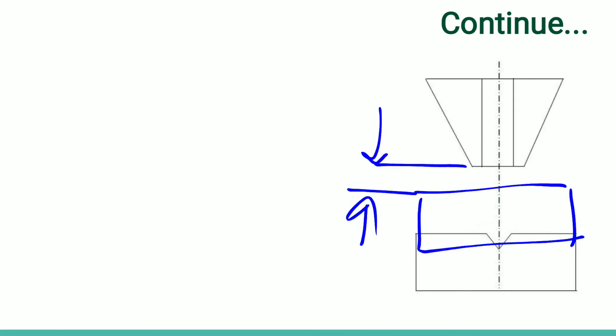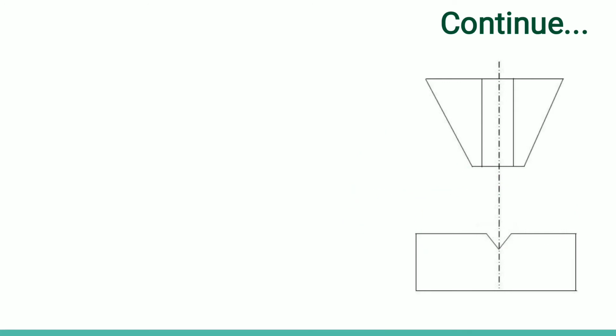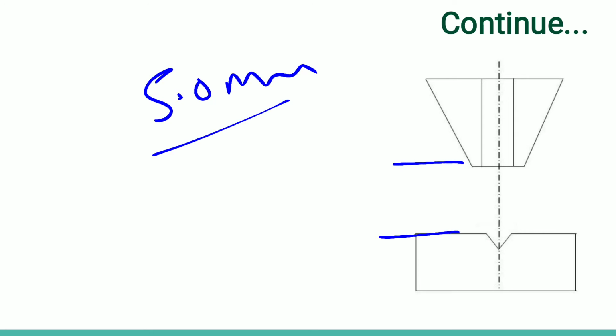So we do not have to allow that, and that's why we need a minimum distance, that is 0.5 mm. Now, the second thing is, if this distance is greater than 5 mm, then what will happen is that the abrasive particles which are coming from this exit will not move straight. This is the straight section that we are using, but it will not move straight,